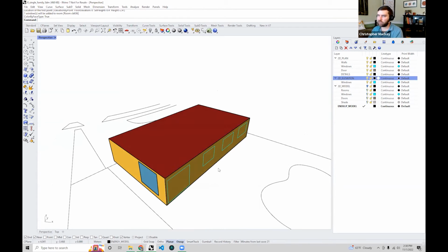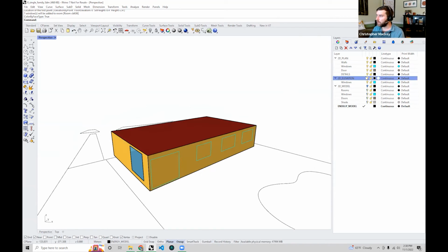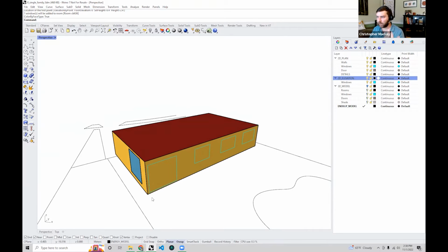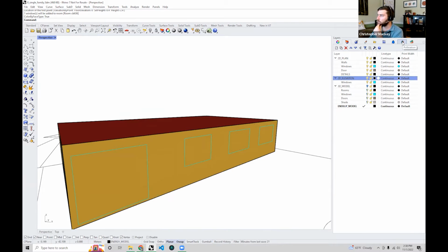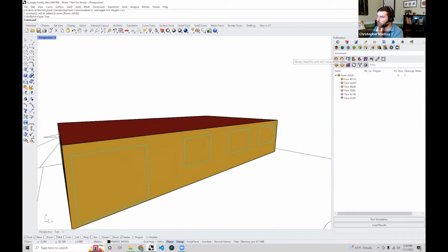And so you can just as easily draw apertures using the elevation as a guide, just like what you do with the plan. So with this on, make sure that you've turned on this 2D elevation line, and I'm going to show you, at least, we're going to draw using the elevation as a guide these windows onto this facade here. So in order to do this, we'll go back over to Pollination, and I'm going to go to draw apertures again. Left click on this little aperture plus button, say draw apertures.